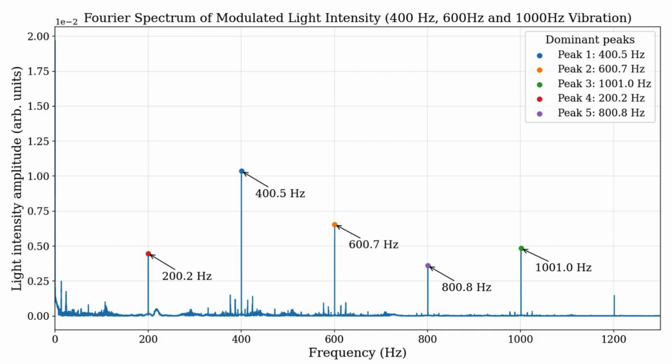But since 1001 Hz also appears in the previous measurement, it is not clear whether 1001 Hz is a consequence of convolution, harmonic distortion, or the actual vibration introduced to the system. Although the system should have captured the 1000 Hz frequency, as the previous measurements imply. Thus, probably the peak at 1001 Hz in this measurement is a consequence of all convolution, harmonic distortion, and actual vibration in the system.